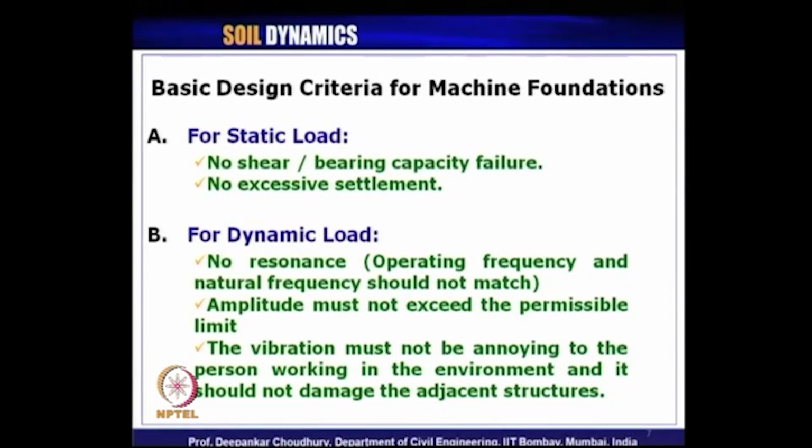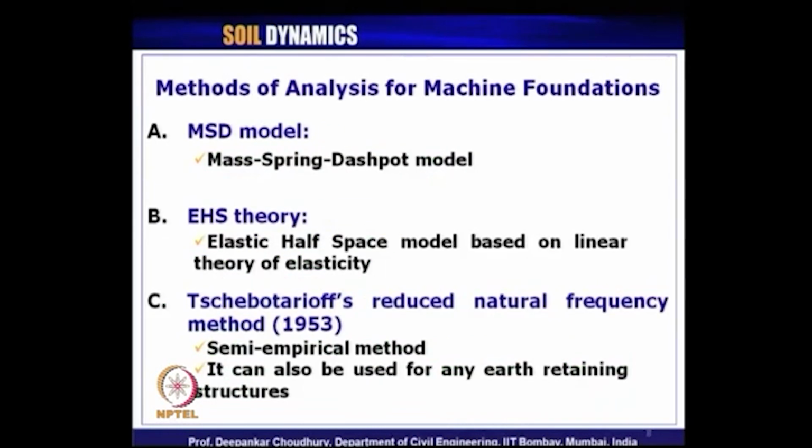Dynamic amplitude must not exceed the permissible limit, and the third criterion is mostly qualitative in nature, which says that the vibration must not be annoying to the person working in the close vicinity, or it should not be damaging to the adjacent structures.